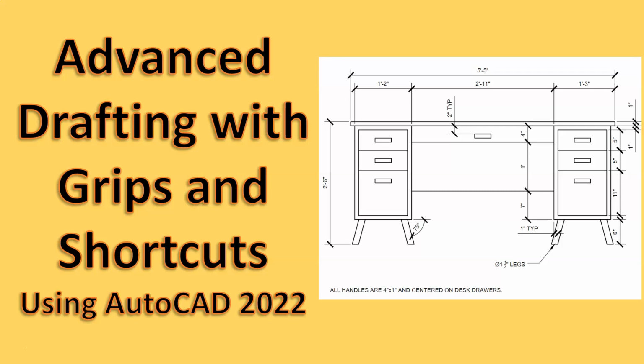I'm going to try to speed this up using some real quick shortcuts, some grips and things of that nature. Hopefully that will help you speed up your keystrokes and understand how to use grips and shortcuts. I will announce the commands, for example, if I want to move something, I will tell you that I'm going to move it. But I'm going to assume that you know how to go to the move command, and I'm just going to use the shortcut by typing in M enter and go on from there. That's what you can expect when I'm creating this desk.